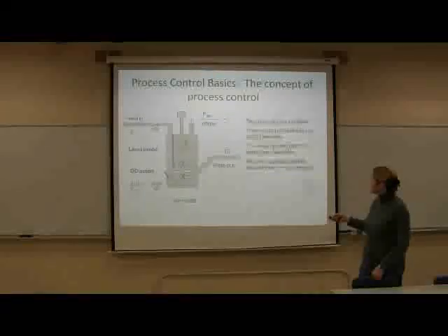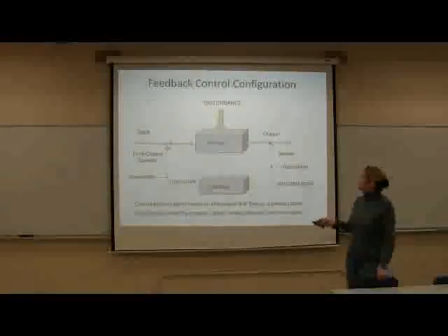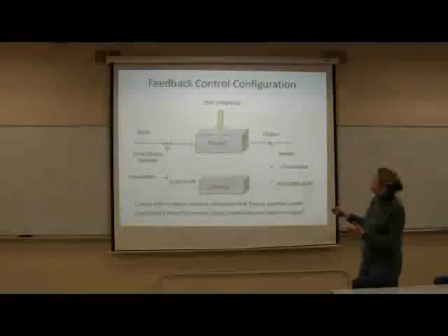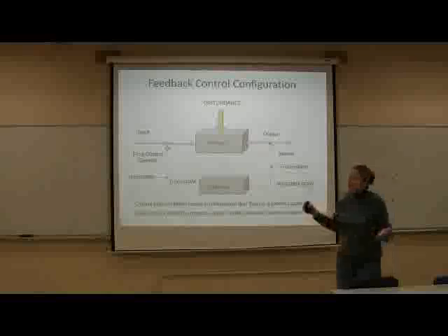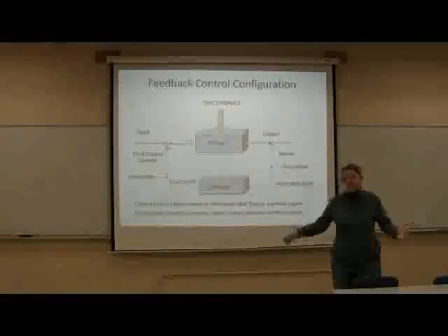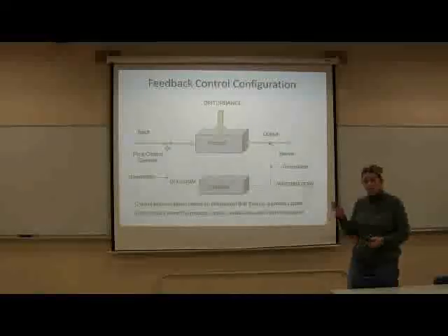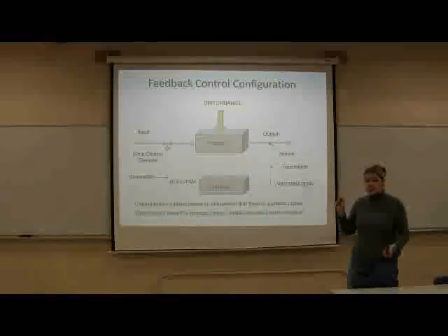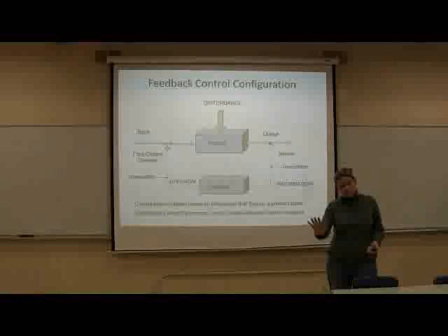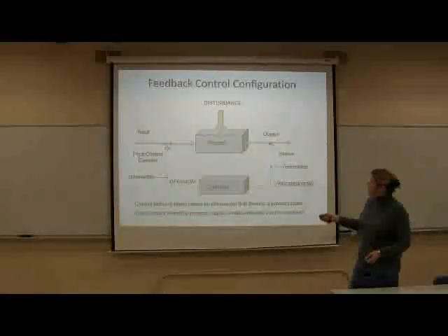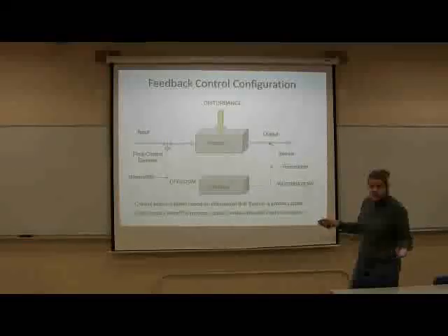Okay, here we go. So this one I'm sure you've seen in your classes, but this is the concept of feedback control. A feedback control in our daily life is using the cruise control in our car. You choose a set point. Speed limit is 65. You choose, say, 70. And you want the car to go 70 miles an hour, but you don't want to have to keep pushing your foot on the gas. So this is going to be the set point. The disturbance would be